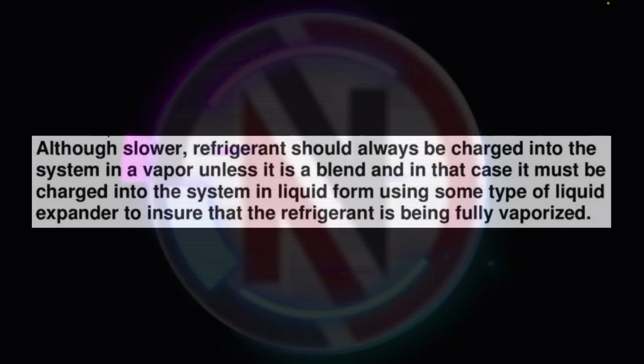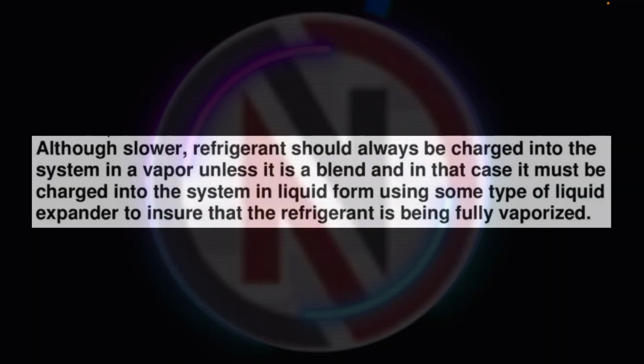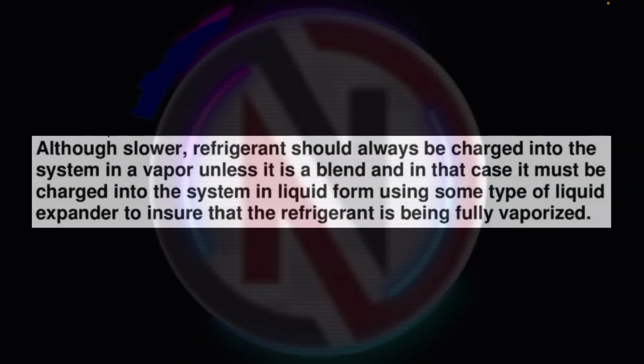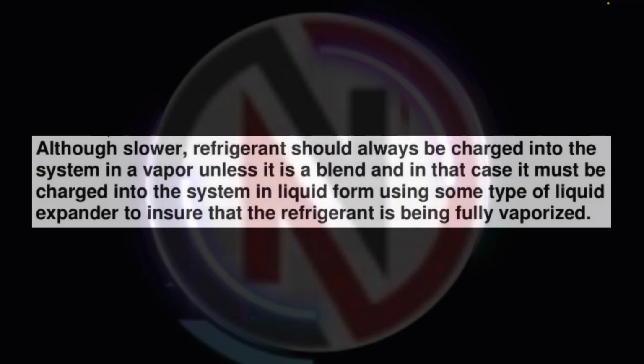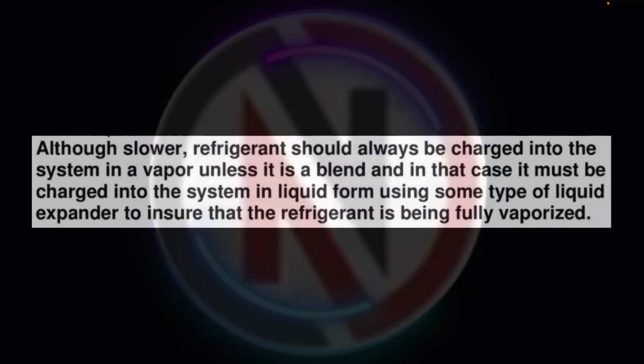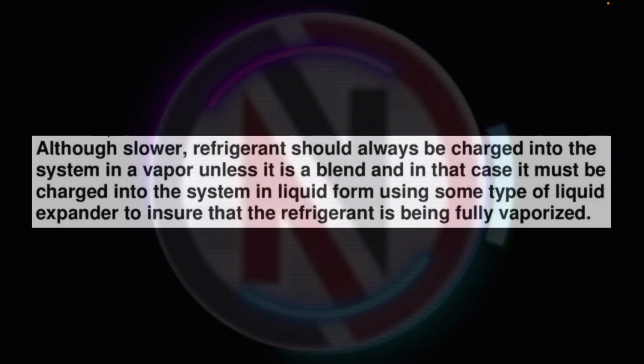Although slower, refrigerant should always be charged into the system in a vapor unless it is a blend, and in that case it must be charged into the system in liquid form using some type of liquid expander to ensure that the refrigerant is being fully vaporized.